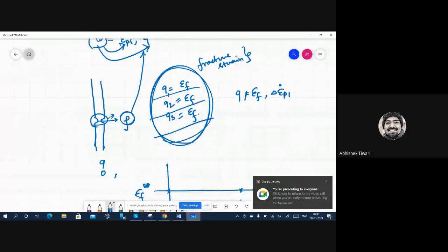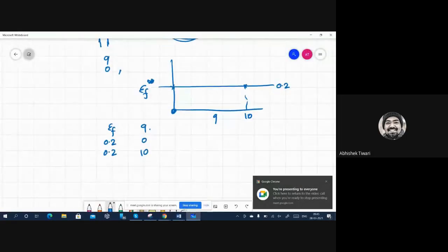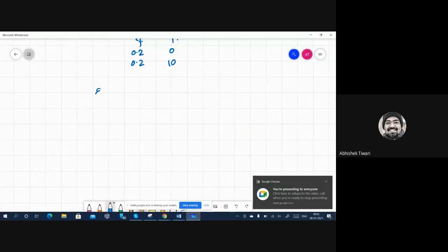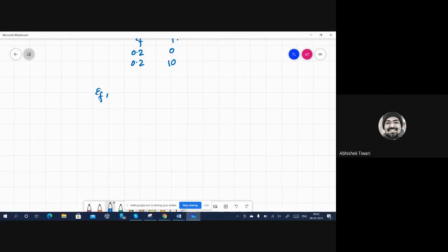That is what we call the kinetics of damage. This is the point where we are defining the fracture strain value, the equivalent plastic strain rate relationship with it, and then stress triaxiality.